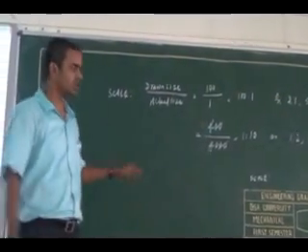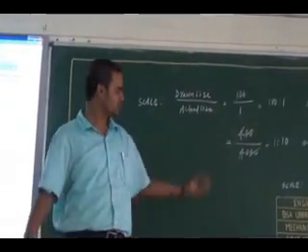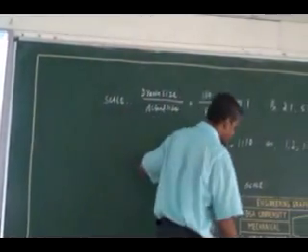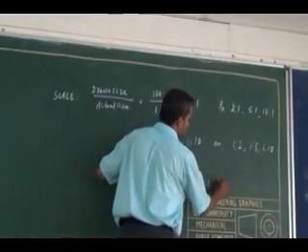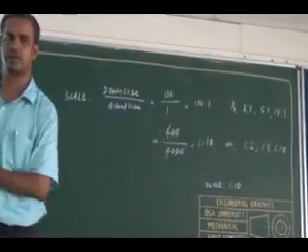In all your engineering drawings, below the components you are drawing you will have a scale written, stating which scale it is drawn to, whether an enlargement scale or a reduction scale. If it is 1:10, I have adopted a reduction scale.